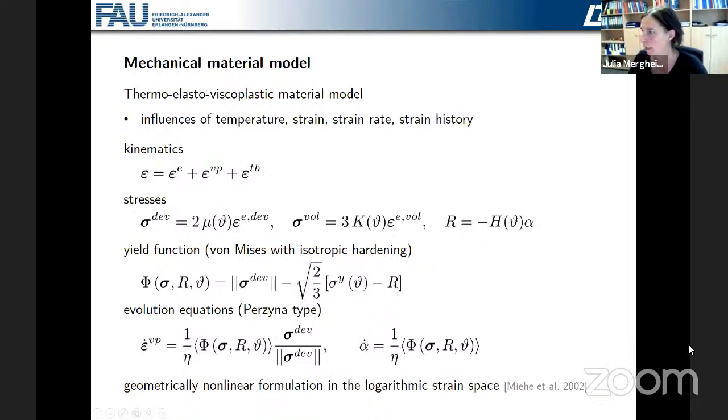Yeah, so that is the only problem. Otherwise, and that's why we decided to use it here. It is equivalent to the multiplicative decomposition. And in this case, actually that was the easiest way to go from the small strain to the finite strain model, because the material model has exactly the same structure. Yeah, and you only have some kind of pre-processing and post-processing step afterwards.